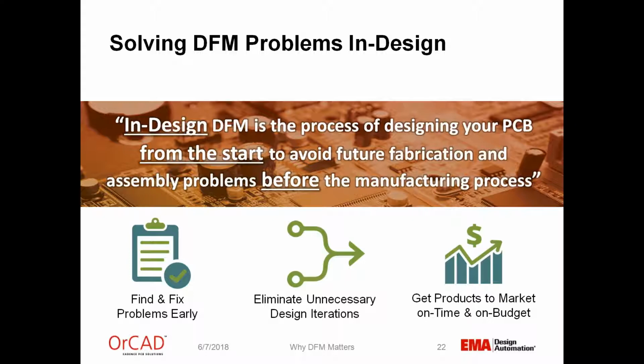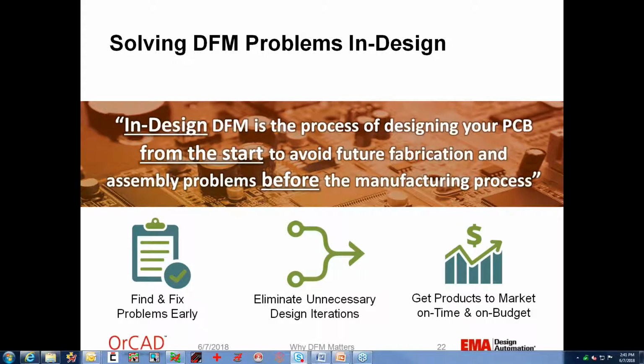Okay, good to know. What is the recommended annular ring to pad ratio? Through my design experience, we used to do 24 mils over the drill size. So if the drill size was, say 60, we would make that an 84, which gives you a 12 mil gap between the hole and the edge of the pad. So that would be a 24 over. All right, looks like we got a few more questions coming in.